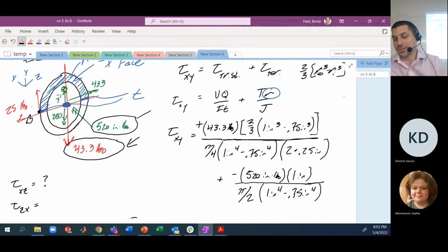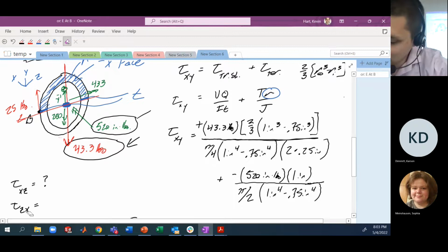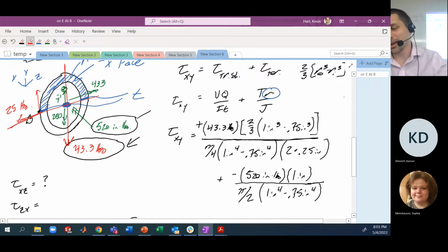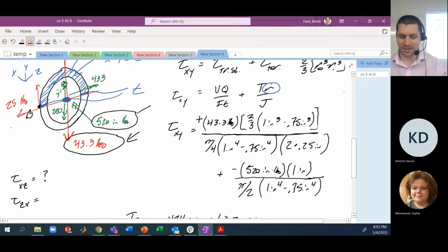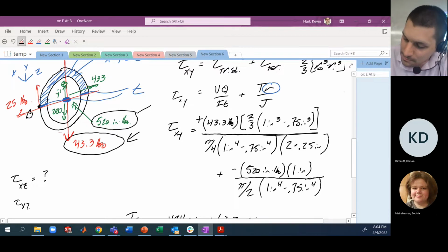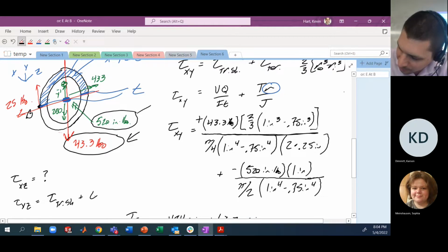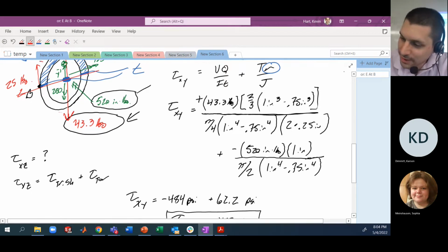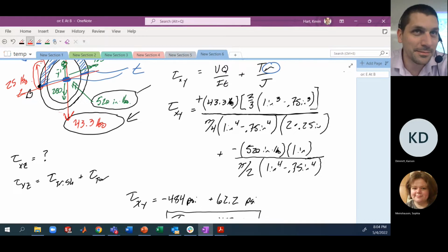You can go through and justify yourself with the normal routes that we've been going through. But here the outward normal at point B of the surface would be generally the z direction or negative z direction. That outward normal is a free face, no stress. You could have some contribution from transverse shear, and you could have some contribution from torsion. We already talked about torsion. We're getting off the highway in the y direction at B. So tau xz, nothing from the torsion. Got it?